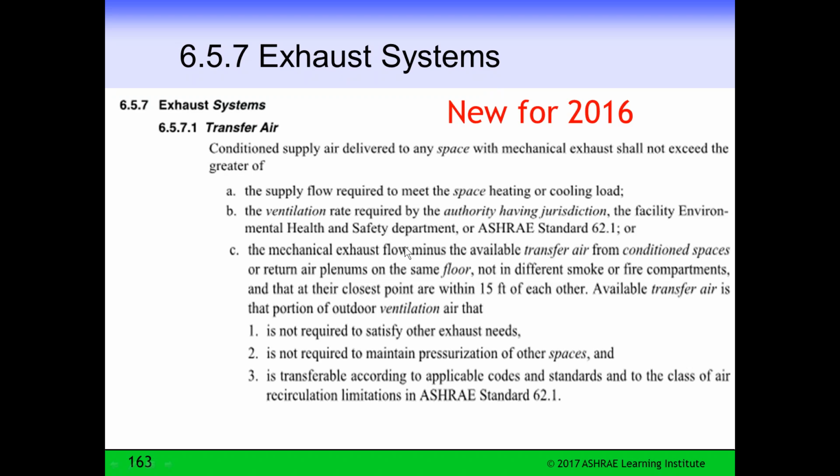Now, exhaust systems, transfer air. This is new for 2016, and it feeds off of what we did in 2010 for kitchen hoods. So conditioned supply air delivered to any space with mechanical exhaust shall not exceed the greater of. So here you've got a room with an exhaust fan in it. And here's how to supply air to the room. The supply flow required to meet the space heating or cooling load. The ventilation rate required by the authority having jurisdiction, the facility environmental health and safety department, or ASHRAE 62, or